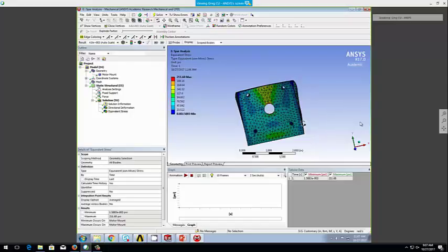Okay, so you should think about this when you're starting to assemble these together. And then here are some length tolerances. So look, under 48 inches can be plus or minus 1/8 of an inch. That's quite long, or a big tolerance, right? So these are things that you should be aware of.